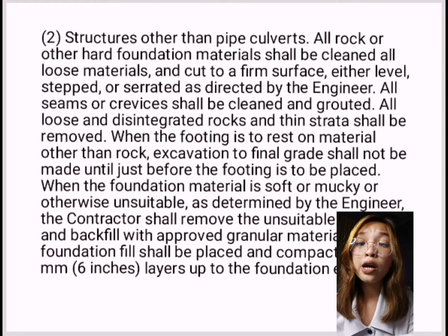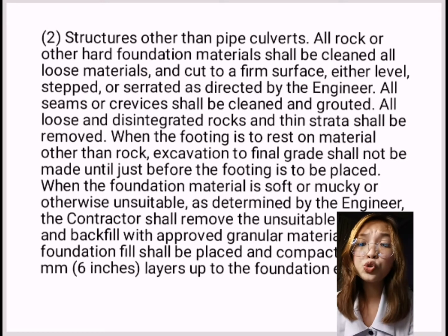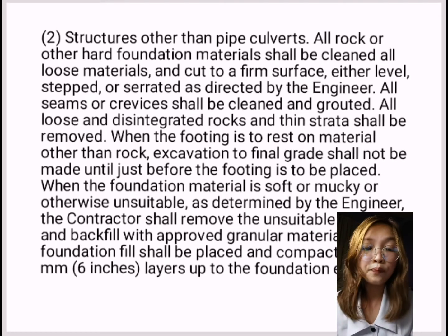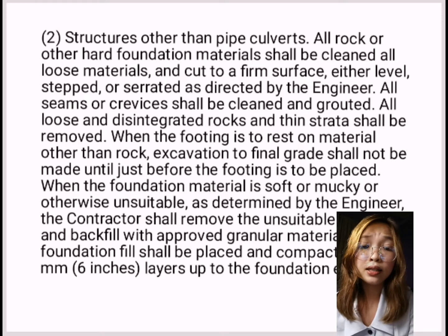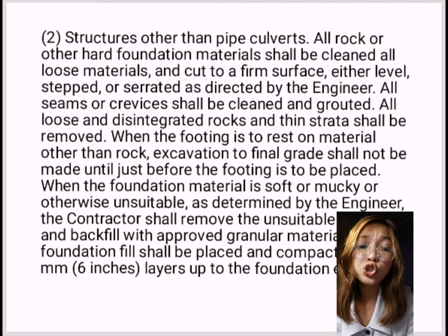All seams or crevices shall be cleaned and grouted. All loose and disintegrated rocks and thin strata shall be removed. When the footing is to rest on material other than rock, excavation to final grade shall not be made until just before the footing is to be placed.